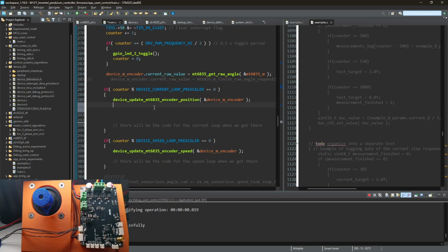So I need to measure. Okay, what do I need to measure? I don't need to measure anything, I just need to calculate it. And what I need to understand is that my single encoder revolution is actually 4 electrical revolutions because I have 4 pole pairs. So my flux does full revolution 4 times.